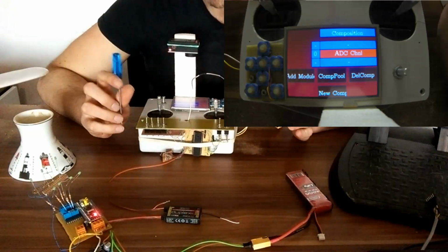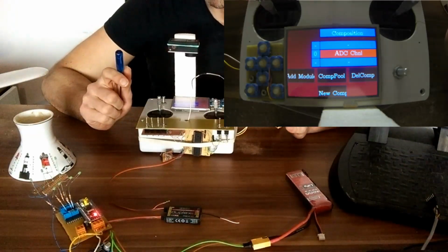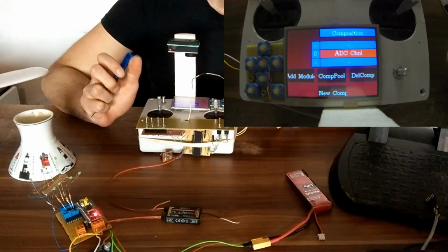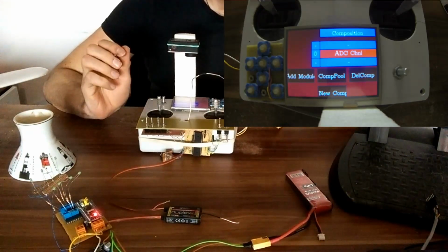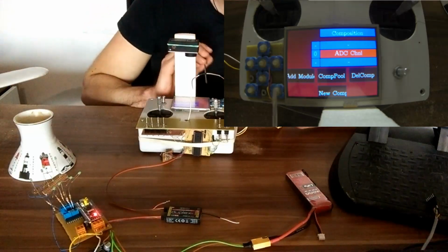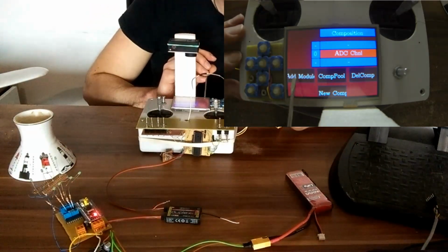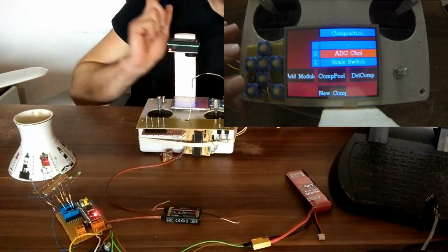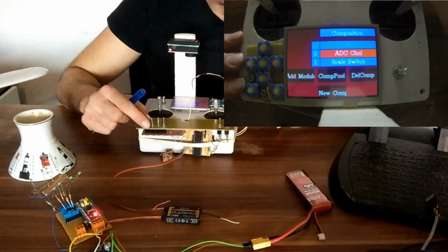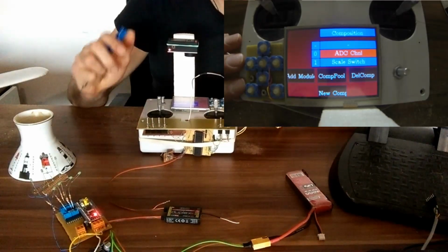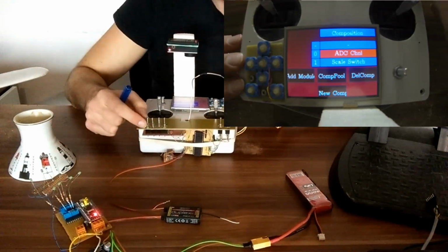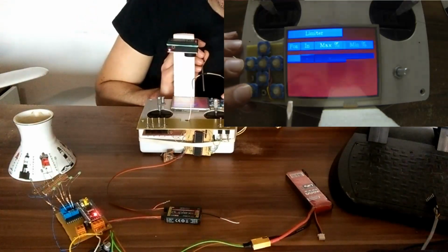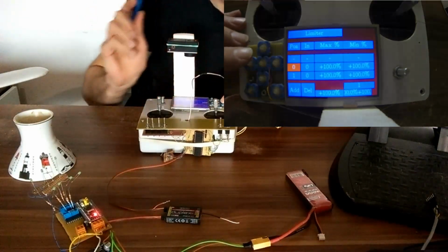As a teacher, you want to have the ability to exclude, to cut off the control from the student to the plane. And the way to do this is, after the input from this channel, I'm going to place a scale switch. And let's say I'm going to use switch number 1 to enable or disable the student's access. So I'm going to the scale switch, I'm adding 2 positions.